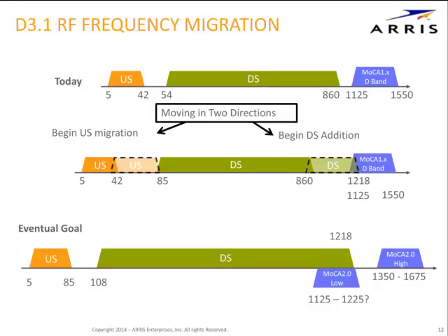It allows the upstream, and this is what is required to be supported in the modems as well as in the CMTS, you don't have to pick it up immediately, but the support is going to be there. There's going to be support on the upstream to go up to 85 megahertz. And on the downstream side, it can now go well above a gigahertz, with the eventual goal, at the bottom of the screen, of showing an upstream spectrum that's been effectively doubled.